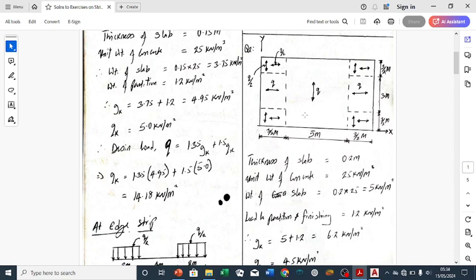The next thing is the load distribution. As usual, the corner is Q over 2, Q over 2, Q over 2, Q over 2. In this x direction, the edge here is Q over 2, and in this direction, at this place, there is no value for Q. Q is 0 here. And in this span direction, Q is across the whole span. Please take note of that.